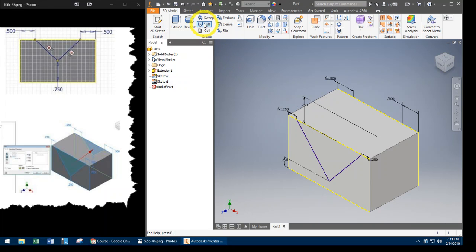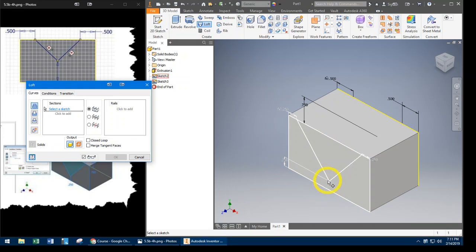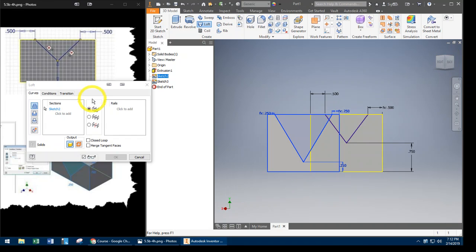The lofting feature requires we do a couple things. First, we're going to add a sketch, so I'm going to select this sketch, clicking on that, and then I want to click in the actual triangle that is going to be my wedge. So that was a 2-click process. At first I clicked the point, and then I clicked the area of the wedge. So that I actually was clicking and selecting the surface, and then that feature is the wedge of that surface. Next, I'm going to flip around to the back side. Going to add another sketch.